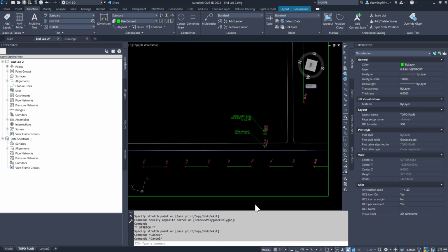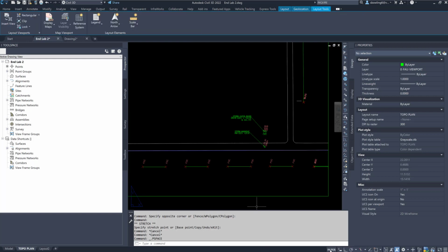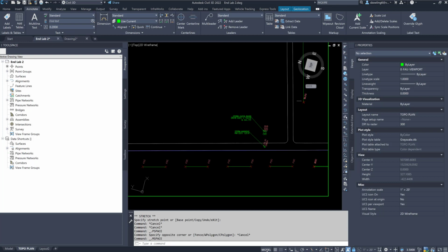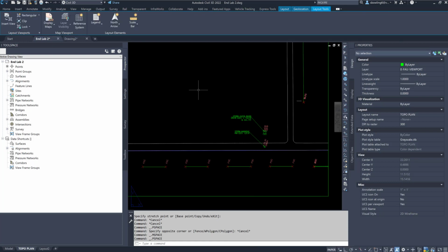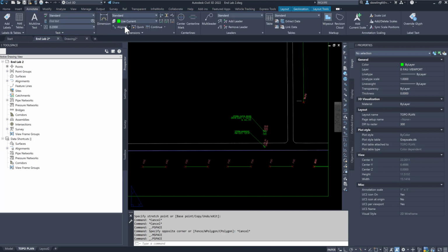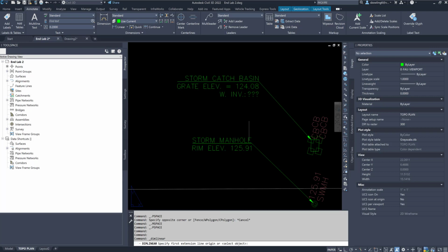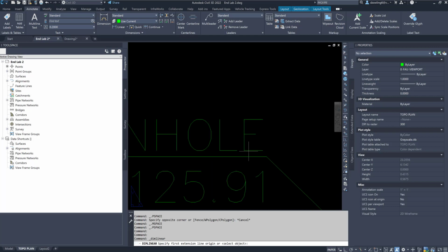Okay. Now I'm going to double click on the outside, and you can see I've gone to paper space here. If I double click on the inside, you can see I'm in the model space here. I'm going to click on the outside and go paper space. I want to show you what I mean by height. If I do the aligned and I measure the height of the text, and I'm just eyeballing this.